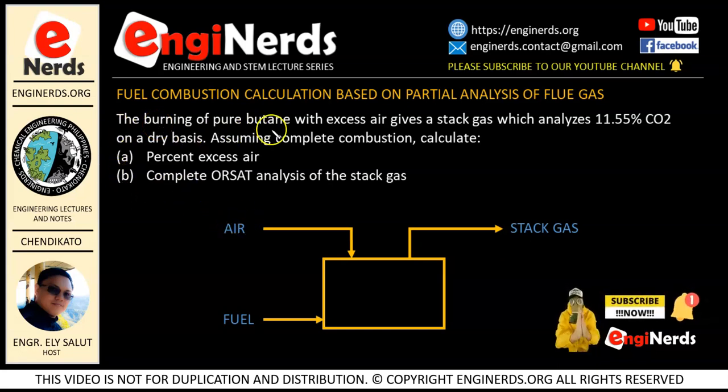The burning of pure butane with excess air gives a stack gas which analyzes 11.55% of carbon dioxide on a dry basis. Assuming complete combustion, calculate A. Percent excess air and B. Complete Orsat analysis of the stack gas.